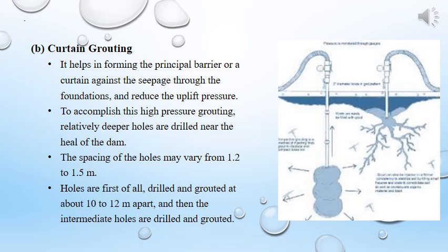The spacing of the holes may vary from 1.2 meter to 1.5 meter. These holes are first drilled and grouted about 10 to 12 meter apart, and then intermediate holes are drilled and grouted.